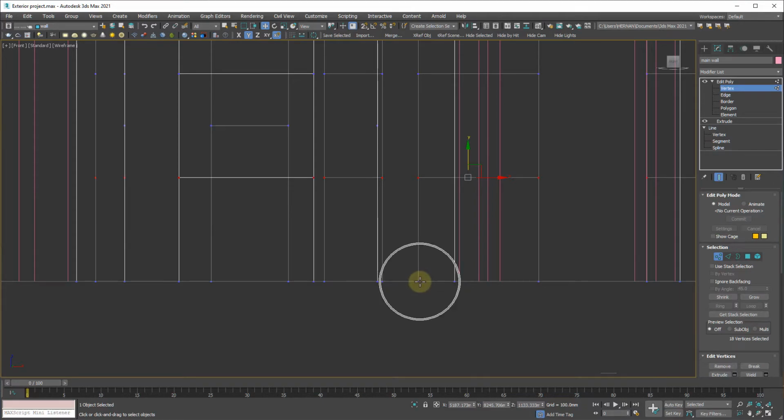So we're going to move this one first to the lower part of your wall, because this is the 0 distance. Then use the move tools, then make sure that you turn on your snap, then y-axis, because we're going to move on the vertical direction. Lock your selection. Make sure that snap appears here or anywhere. Then pick your point somewhere here, then move downward, align them to the lowest part, which is your 0. Then we move it upward.